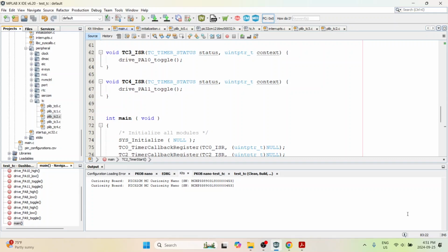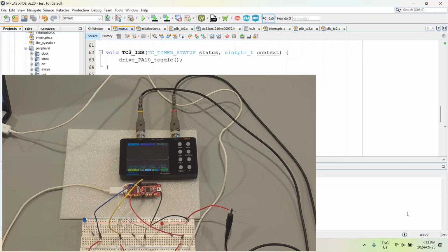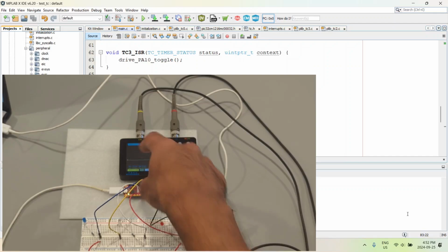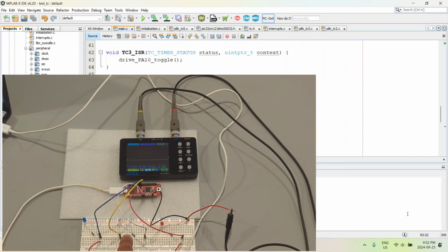just the microcontroller and the breadboard, there is also the oscilloscope. Because remember, there is one timer with a 1 millisecond time interval, and that can only be viewed on the oscilloscope. So you can see the microcontroller in the video, and as you can see there is also an oscilloscope that has been added. Now most of the connections are the same except for this one additional connection from PA11, and I have taken it out to this wire where I am taking it out as a connection which I can view on the oscilloscope probe.